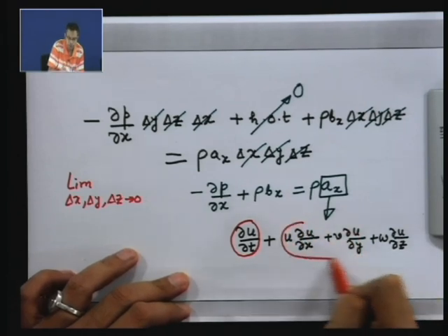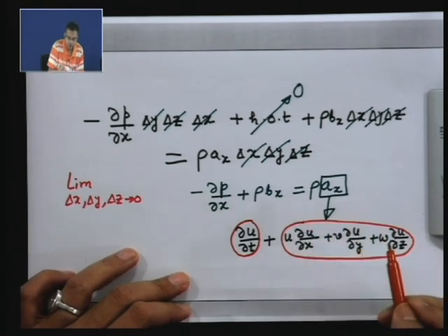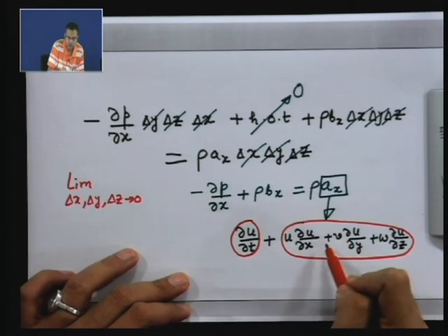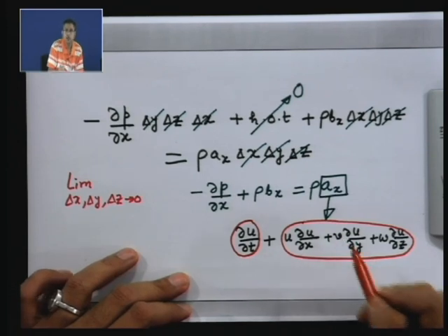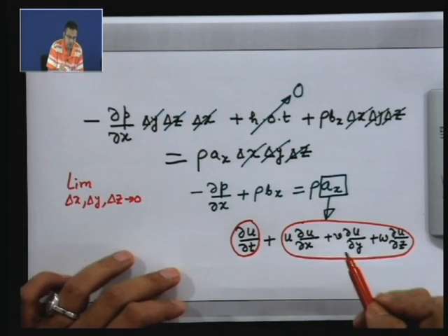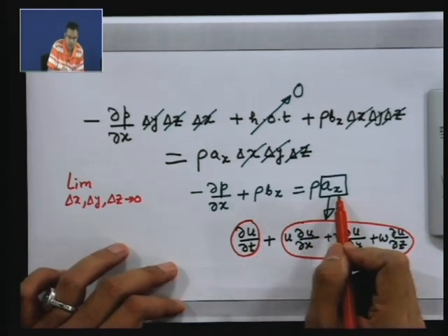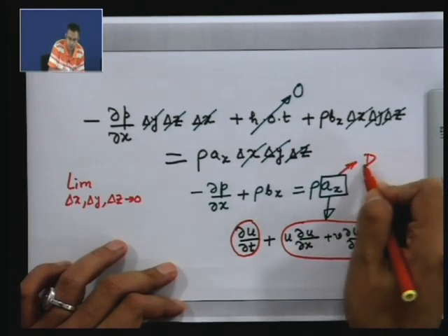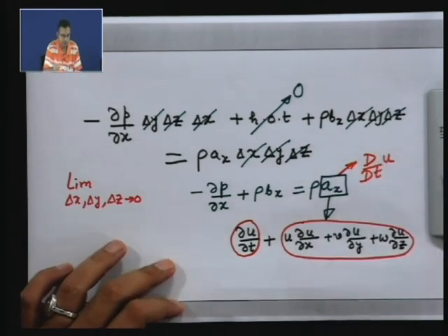So, that is the temporal component, and it is the advective component because of the change in position, change in velocity with respect to position, you encounter a different velocity field and that gives rise to an acceleration. So, these two effects combined together give rise to the acceleration of flow. So, this is also written as capital D Dt of u, this was explained yesterday.